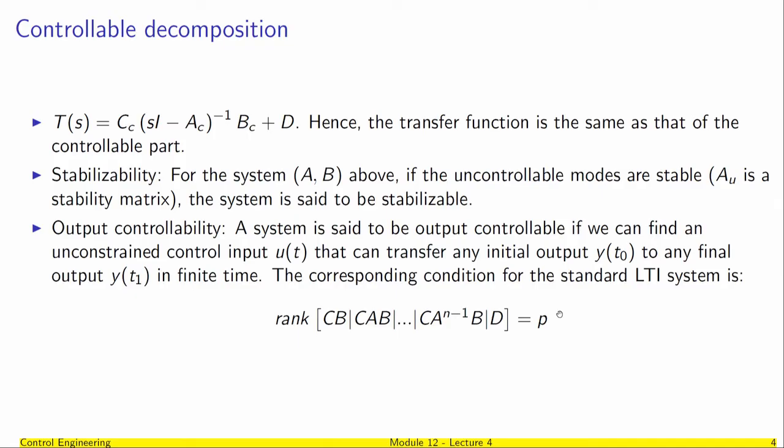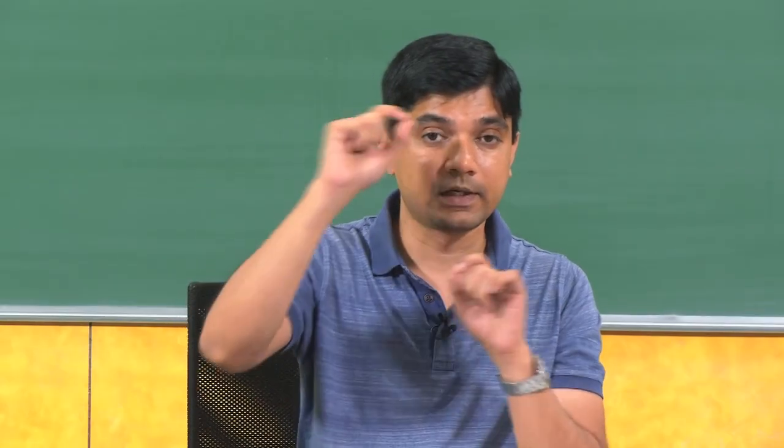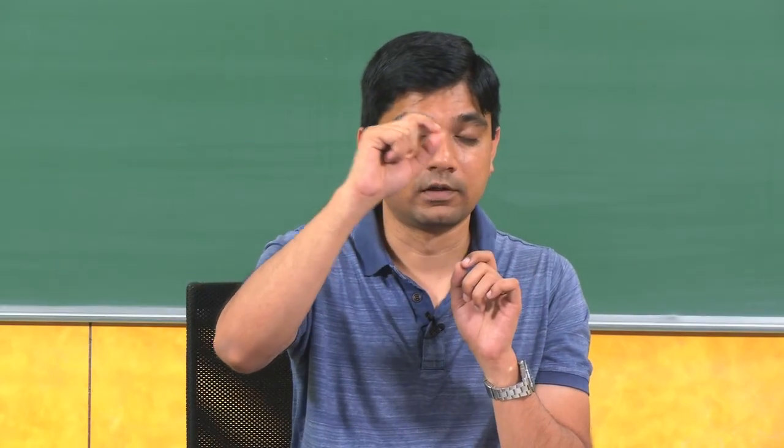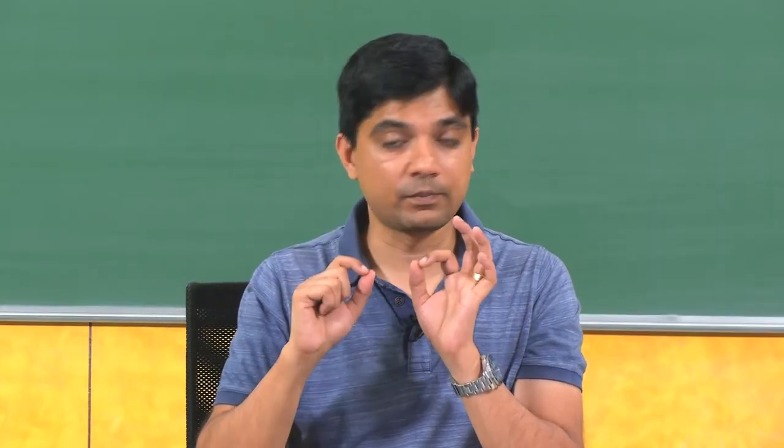Okay. So, what have we learned here? What do we do if the system is not completely controllable? If the system is completely controllable, I can just use u equal to minus kx to achieve the desired performance in terms of placing the poles at their appropriate locations. Even in root locus, we were just shifting the poles, shifting the dominant poles to the left if you wanted a faster response, and also the poles when we were doing the lag compensation. So, we are essentially playing around with the poles. This is also something similar.